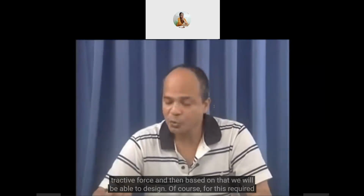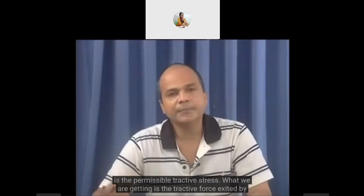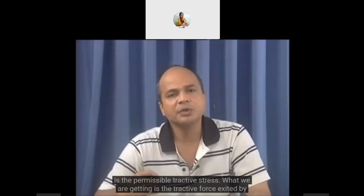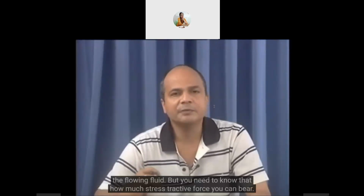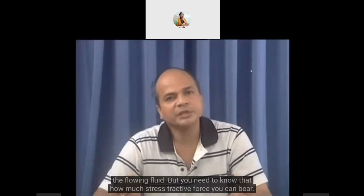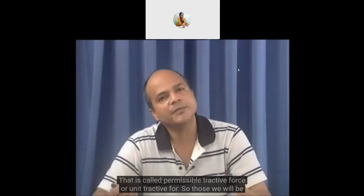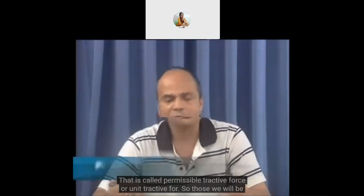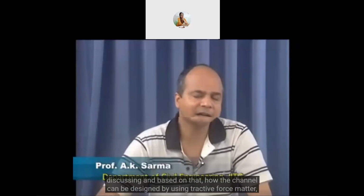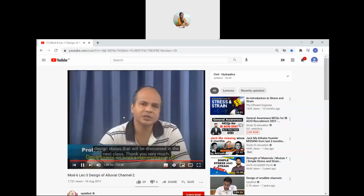Of course, what is required is the permissible tractive stress. What we are getting is the tractive force exerted by the flowing fluid, but we need to know how much tractive force the channel can bear. That is called permissible unit tractive force. Those we will be discussing, and based on that, how the channel can be designed by using the tractive force method, the design steps, we will be discussing in the next class.